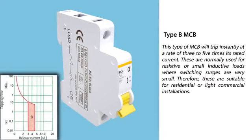Type B of miniature circuit breaker. This type will trip instantly at a rate of 3 to 5 times its rated current. These are normally used for resistive or small inductive loads where switching surges are very small. Therefore, these are suitable for residential or light commercial installations.